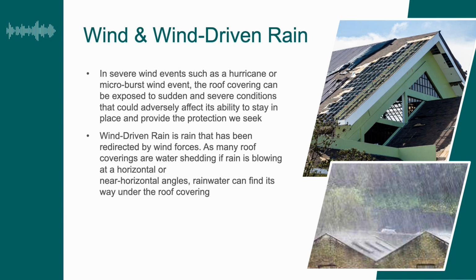And it really helps if you're using a secondary water barrier, such as strips of self-adhesive over the plywood joints. At least if you lose your roof covering and maybe lose part of your underlayment, the theory is you'll keep the damage to the inside of the building at a bare minimum. So even if the job wouldn't afford you the opportunity to use a self-adhesive underlayment over the whole building, at least you could use it on the joints in the structural deck.